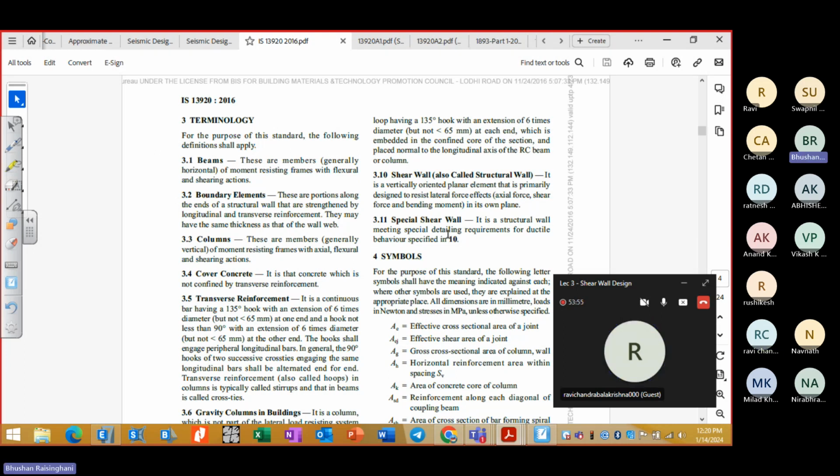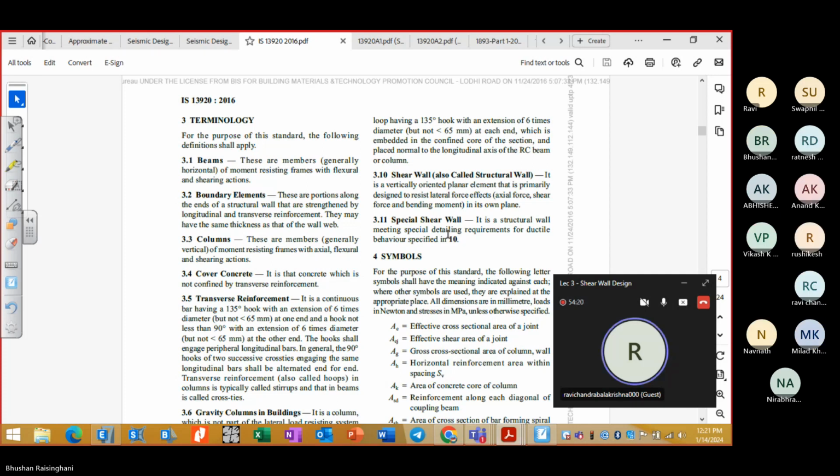Okay, so there is no option to read the in-plane moments. We only assign the wall as a shell element, and we collect the F22 forces. But how could I read the in-plane moment forces? Or else I can only check with stresses.